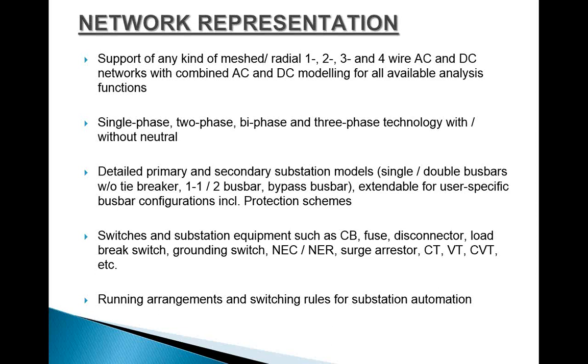Detailed primary and secondary substation models are there. Single and double bus bar with tie breakers, bypass bus bar, and two bus bar systems. Those kinds of GUI tools are available, and the tabs for buses are also extendable for user-specific bus bar configuration. If you want to put circuit breakers and different protective schemes on your buses, you can just drag them from our library and put them on our buses.